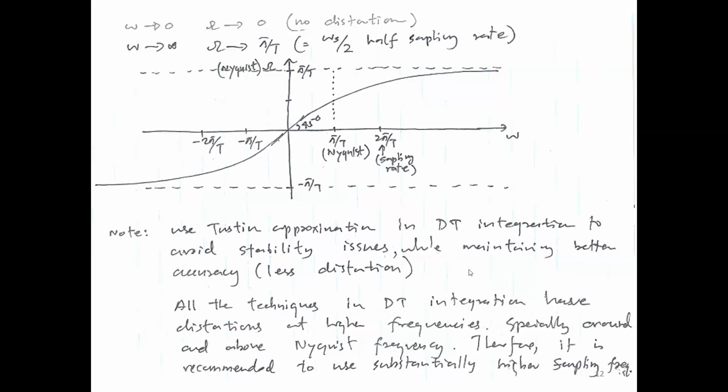So here, what the graph would say is if we are considering only until the Nyquist frequency, we don't want to consider the rest of the graph. Yeah, partly yes, but I don't want you to go even to the Nyquist level, right? Maybe far below that, maybe a quarter of the Nyquist limit is a good choice so that it will be more linear, right? In fact, this is not a linear curve at any point. It is entirely a non-linear curve, but it is more and more linear when you go closer to zero. So therefore, if you stick to your frequencies, maybe 1/3 of the Nyquist or 1/4 of the Nyquist, smaller the better. Smaller the better.